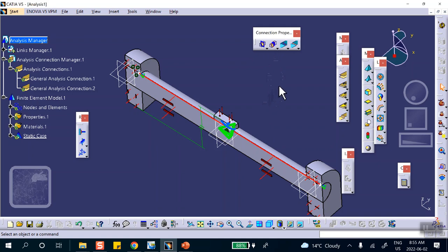What kind of a connection is this? If you bought this shaft and brought it home and stuck it into there, what would the nature of the connection be? This is saying they're friends and enemies and relatives and things like that. It doesn't say how. Connection simply means there is a relationship between this guy and that guy, this surface and that surface. It doesn't say how. If the problem statement says these are fully bonded, that end that I put in there is fully bonded, fully glued, whatever, then it's going to be faster. Otherwise, it's a contact connection.